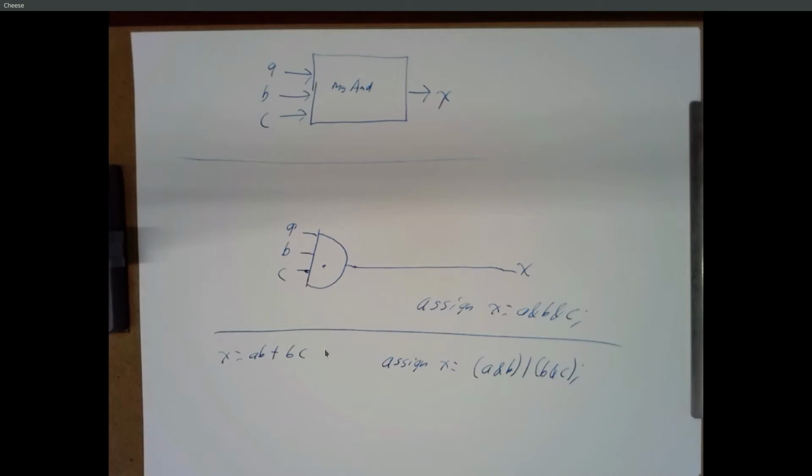And more, this is how circuit design is done, right? It's using Verilog to design the circuit and then using something like programmable logic to actually implement it. The programmable logic is nice because if I really wanted A, B, or B, not C, right? Well, if I take my Verilog and send it to a chip manufacturer and they make a chip for me, and I test it and it's not working, and I go through my code and debug and say, oh yeah, I really meant B ANDed with C bar, I just wasted a few $1 million.